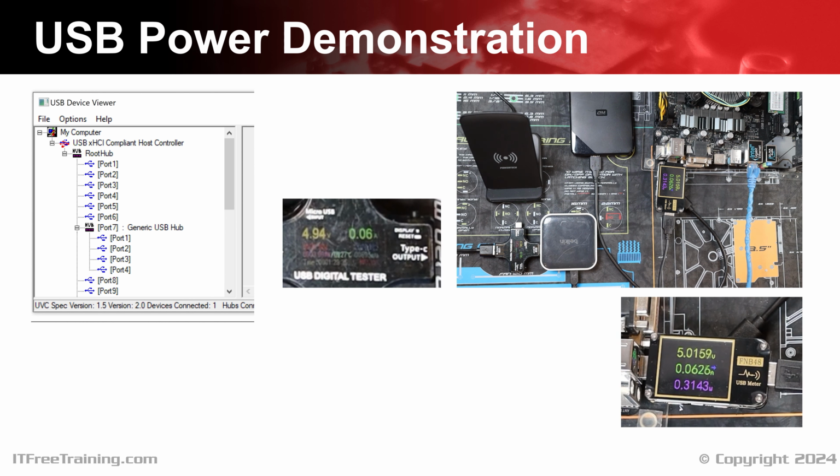I will next put a phone on the charger to charge. Devices like phones when charging will draw a lot of power, since most people want their device to charge quickly. Since it's only drawing power for charging, it won't be detected as a device in the computer. The power will go above 500 milliamps because the phone will pull as much power as the motherboard lets it.